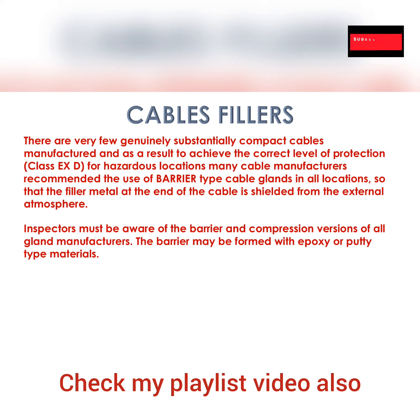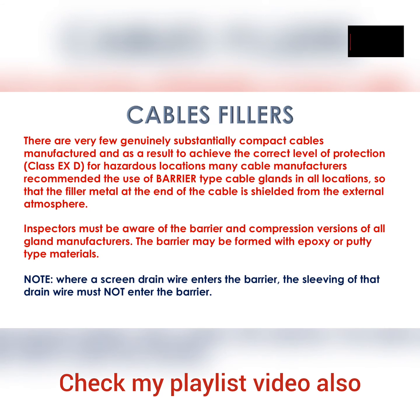Note, where a screen drain wire enters the barrier, the sleeve of that drain wire must not enter the barrier. Okay, we'll show you all this information throughout our presentations, and also in our previous videos and the next videos as well, because this is a big topic about the cables.